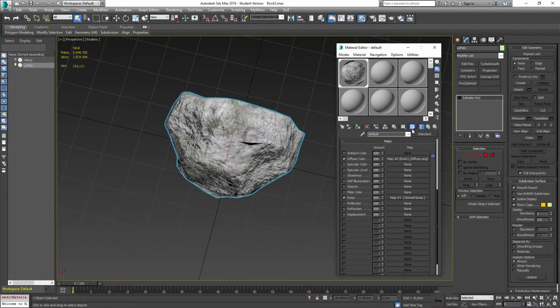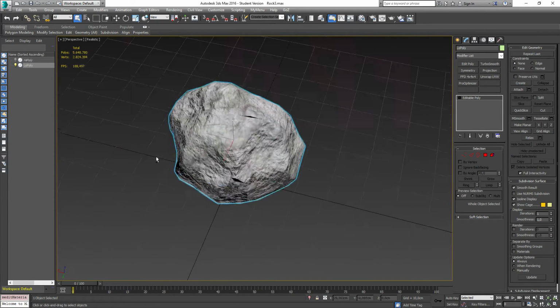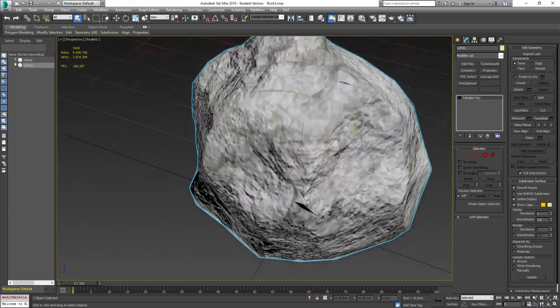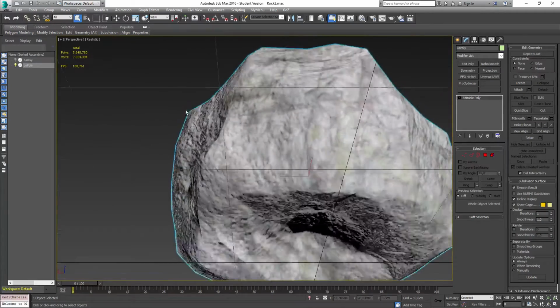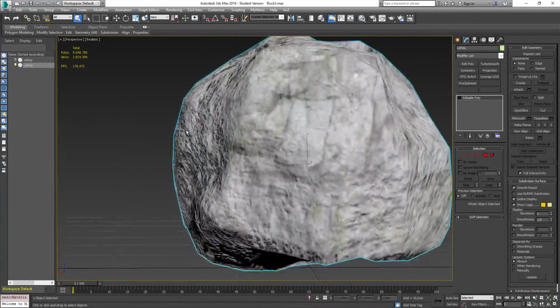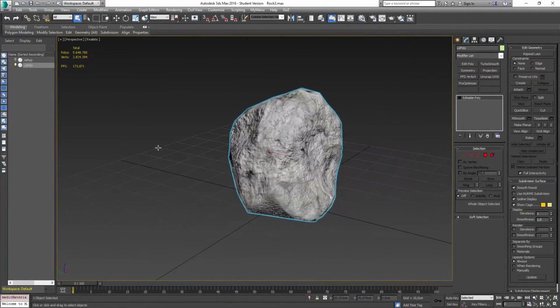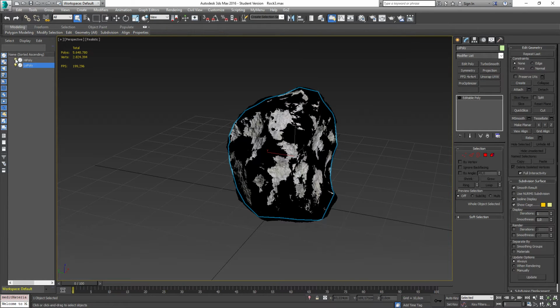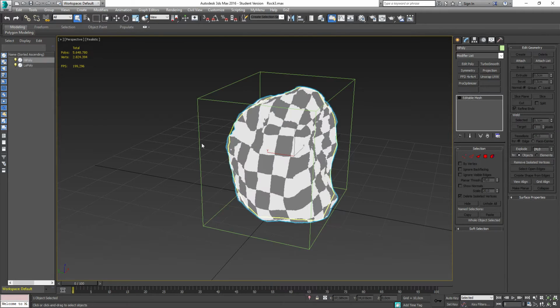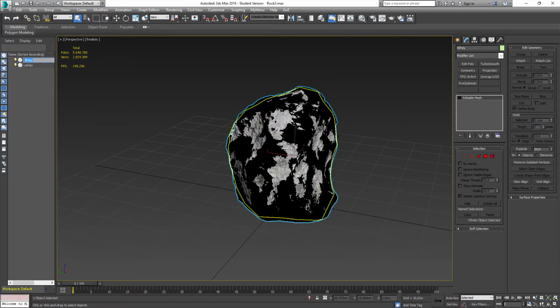Oh, there we go. So apparently it's "show realistic material in viewport." You have to hold this one down and then move to this one. Okay, great. Good to know. So now we have some of that detail back. All this bumpiness that we got from the normal map, or from the high poly. So we can take the high poly now and throw that out.